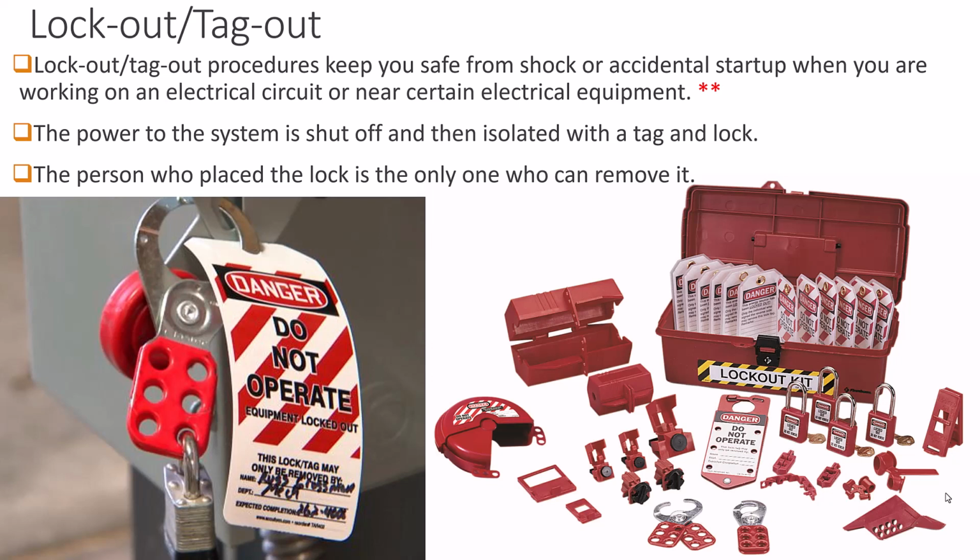And generally in the plants, they will use a very specific lock and have a rule that nobody else is supposed to have a lock that looks like this, so that everybody recognizes through their safety training that that lock is something that you're not supposed to be messing with because it's a lockout tagout lock. And generally you'll also have their name or a number that identifies the person, identifies the lock, so you can tell who the lock belongs to.